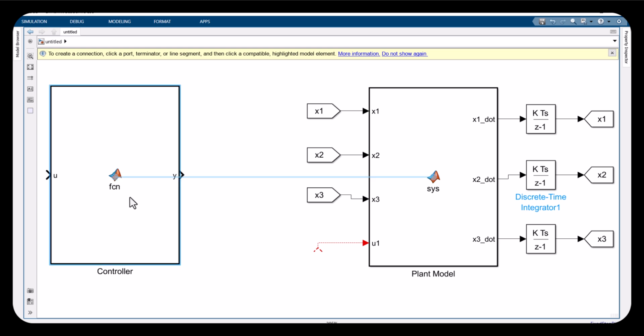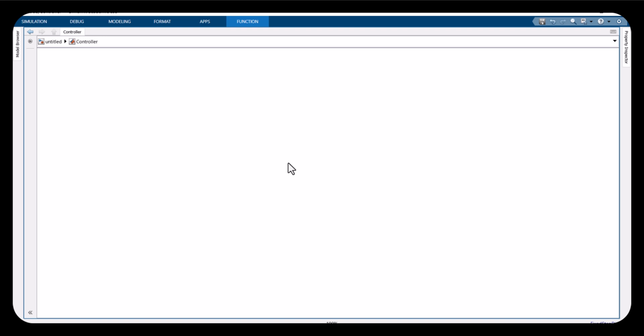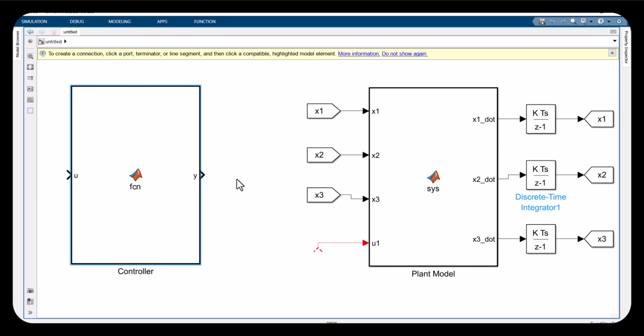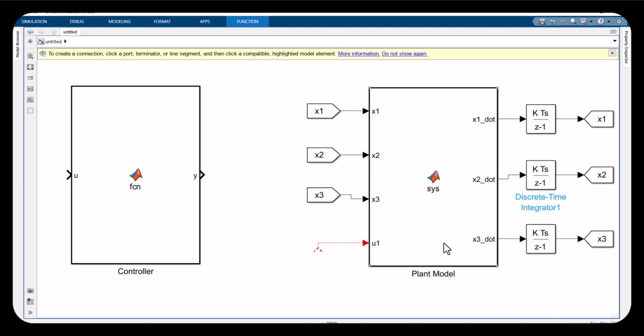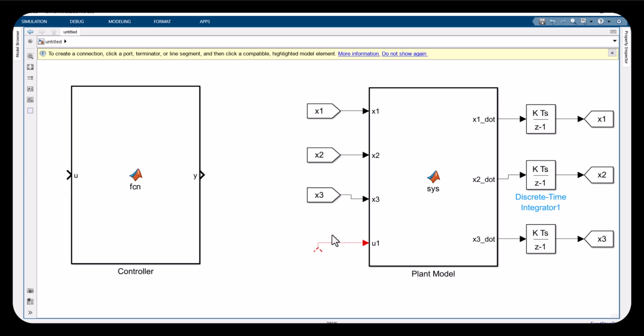So here we designed another part, the controller part. It was another MATLAB function, so we'll just go ahead and open this. Today we'll be implementing the sliding mode control, the basic sliding mode version, and we'll see how it behaves for this system. For now, we cannot just run this system, because the equations will not be computed since it is incomplete. We do not know the value of u, and for what time it should be, we do not understand that.